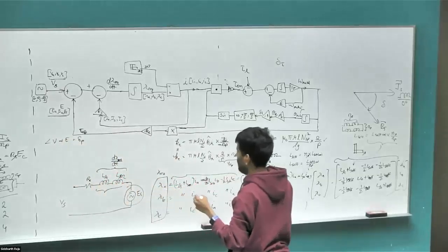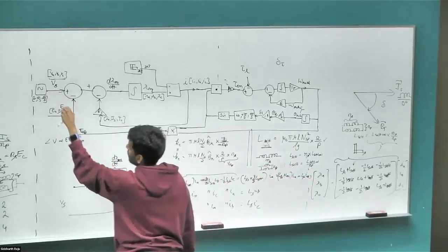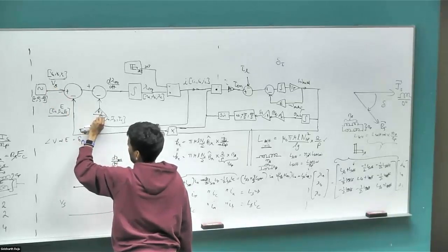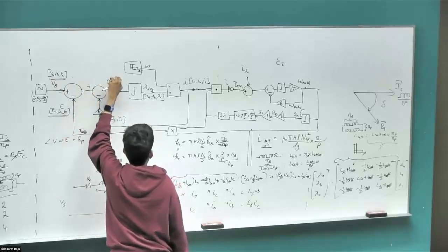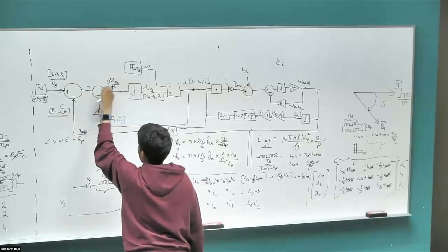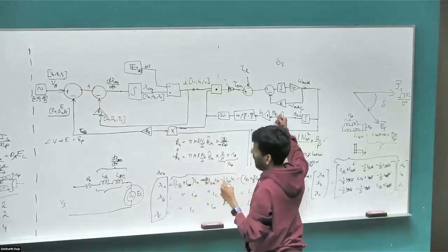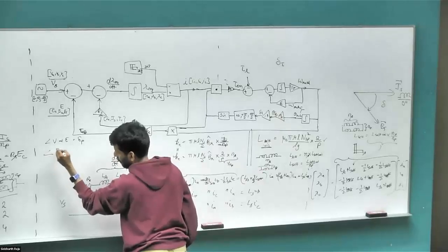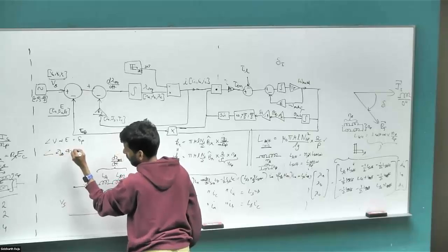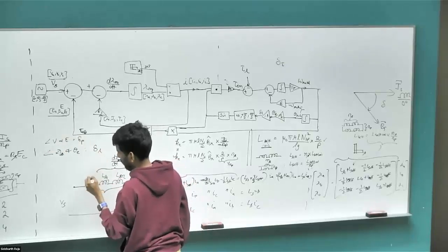Now, if you want to figure out the angle between BA and BR, what it would basically do is figure out this voltage minus IsRs, you'll get some voltage, integrate that, and you'll get the flux linkage lambda. Figure out the space vector lambda S flux linkage, not just lambda MS. And the angle between lambda S and theta electrical, that is the angle between B air gap and your theta E. That is going to be your delta L, which I indicated in one of the space vector diagrams.